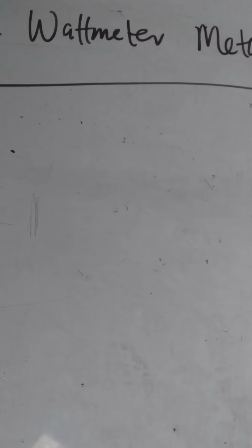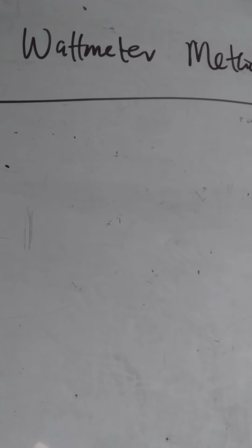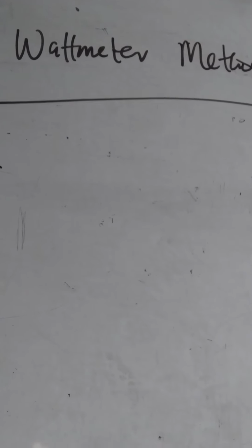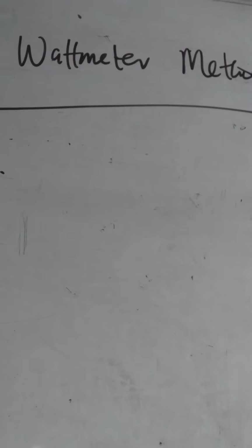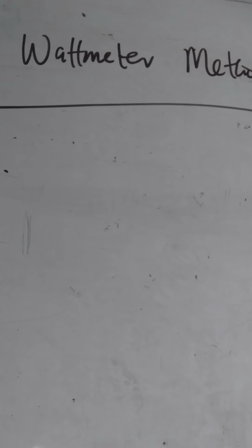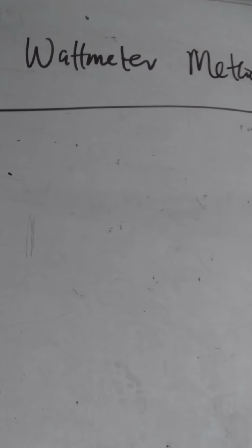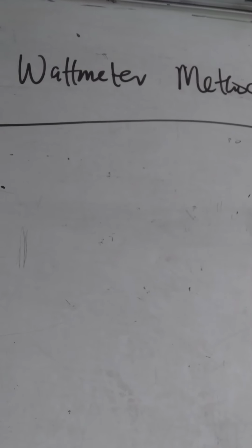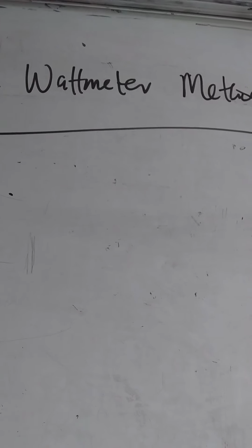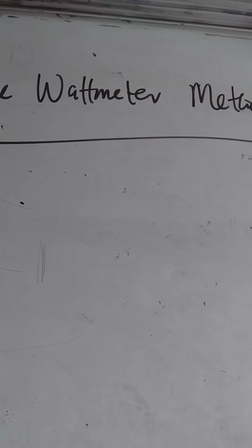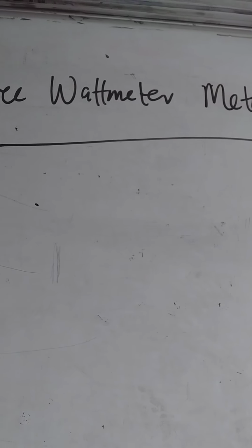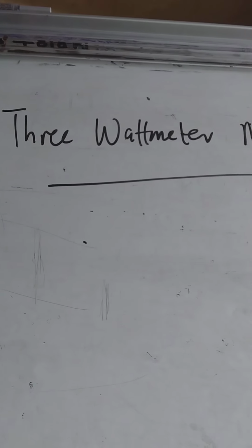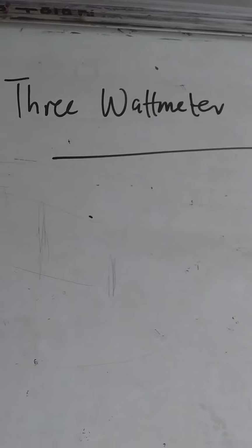If it is a three-phase, 4 wire, star connected system, you connect the voltage leg to the neutral wire. But if it is a three-phase, 3 wire, star connected system or a delta connected system, you connect the voltage legs to each other. You connect it so that it forms something that looks like a star connection.